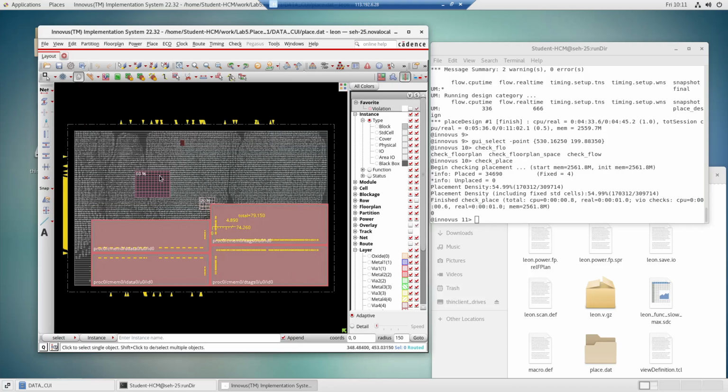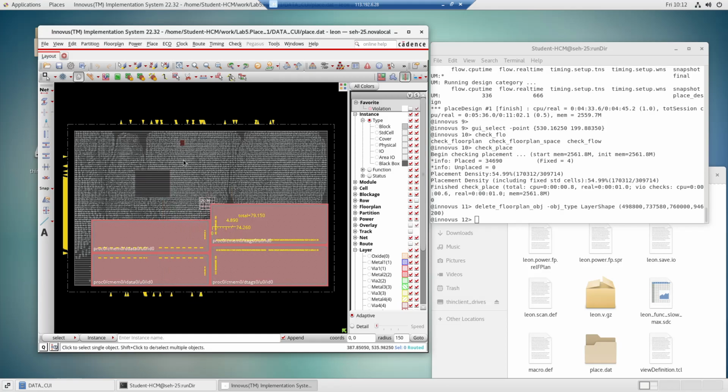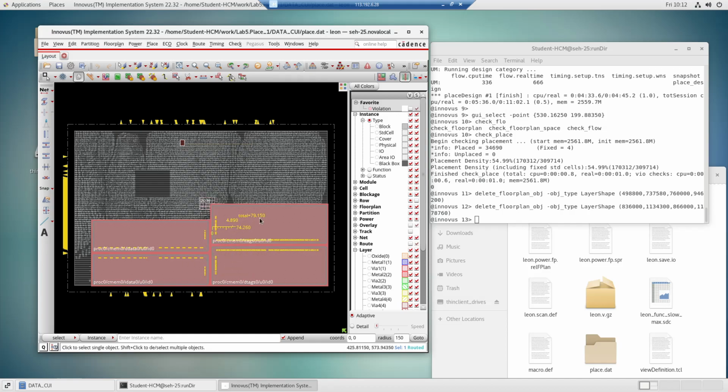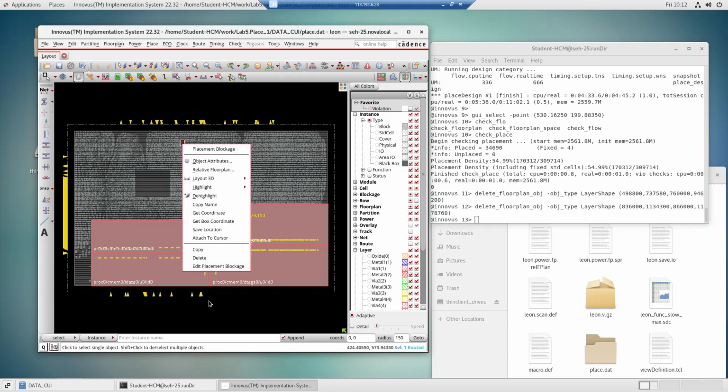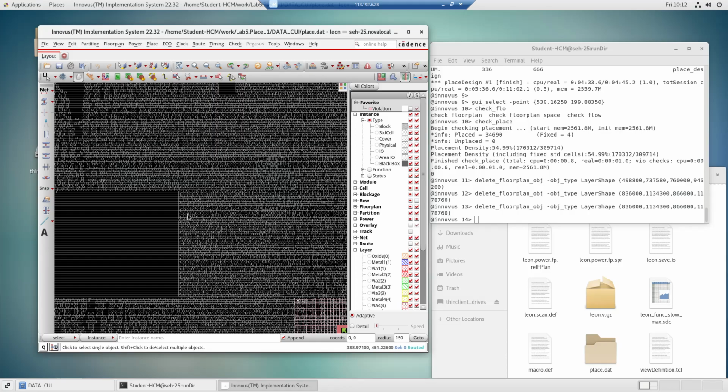What Ting was talking about is that you can use a hierarchy related to your netlist and set a density screen per module. If you know a certain module has a high pin count, you can look at the placement, see if it's placed in groups, set a density screen based on that, and limit the density in that area.